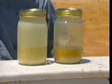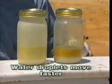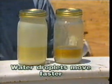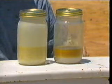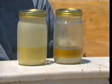Heat alone will not break an emulsion, but it aids in several ways. Heat causes the water droplets to move around faster, striking each other with greater frequency and force. As the droplets collide, the film of emulsifying agent ruptures and larger, heavier droplets form. Now, these larger droplets yield to the gravity differential and gradually settle out.